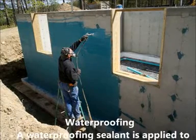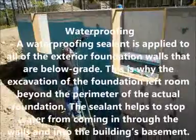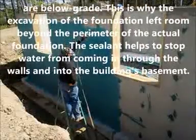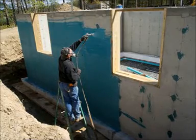Waterproofing. A waterproofing sealant is applied to all of the exterior foundation walls that are below grade. This is why the excavation of the foundation left room beyond the perimeter of the actual foundation. The sealant helps to stop water from coming in through the walls and into the building's basement.